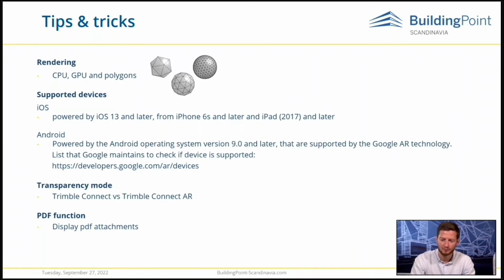Short tip regarding reinforcement and embeds. Where if you would like to, for example, use the AR in a factory, the AR transparency mode works a little bit differently than transparency mode in Trimble Connect. So in order to see the reinforcement or embeds inside an element, we need to actually hide the layer responsible for geometry. And